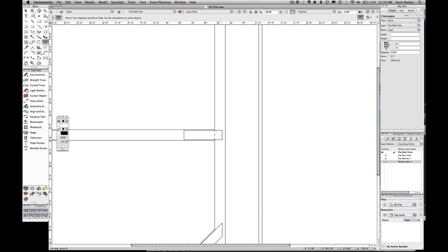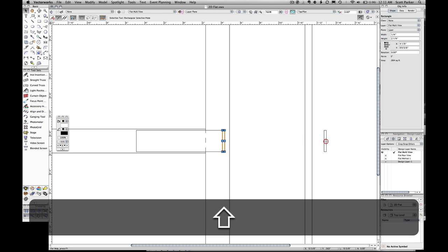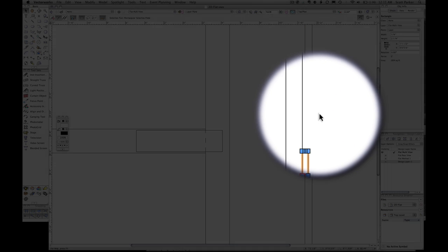We need to throw in the side of our toggle, which is basically a small 1/4 inch box. Missed the mark. If you ever miss a mark, hit delete or backspace and it just backs you a step. So we'll pull this down. It's going to be 0.25 for the first number. Click. I'm going to grab it and simply move it out here. Just line it up. Bring it back so that it snaps to our object.